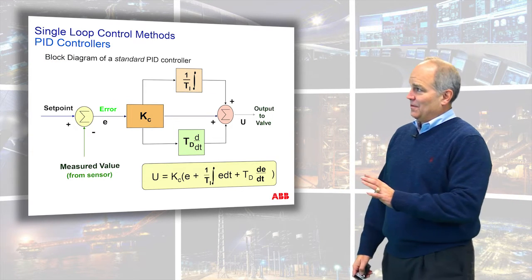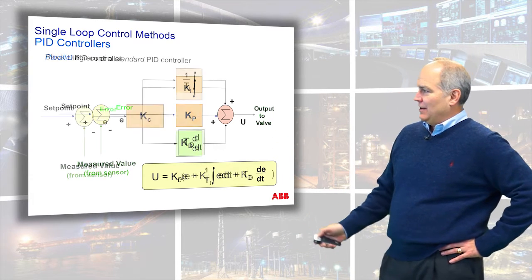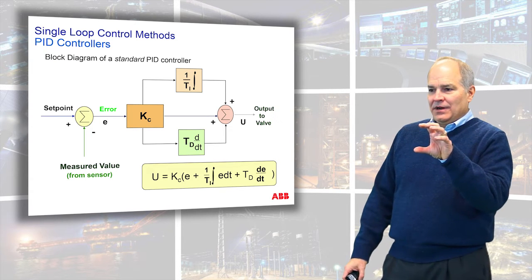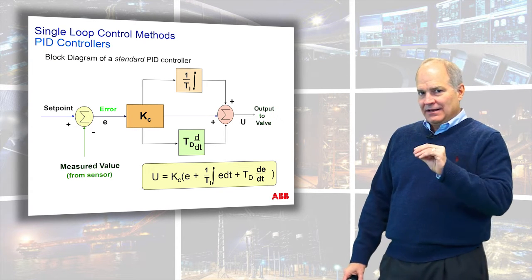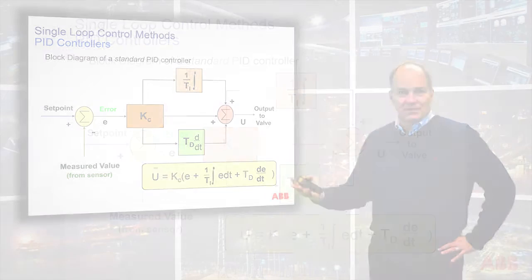The standard form of the PID algorithm, if you look at the block diagram, here's the parallel, then you go to the standard. They literally just slid the gain back to where it gets applied to all three lines. So you can see here in the math, you've got these parentheses. So they literally took the control gain out, or applied it to each one, in other words. So you have the control gain times the error, and then the integral of that, control gain. So it looks like it's really messy.